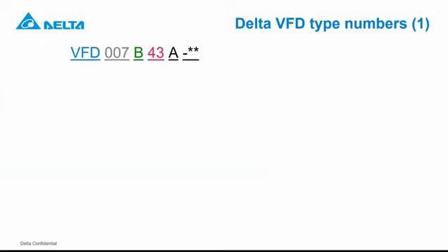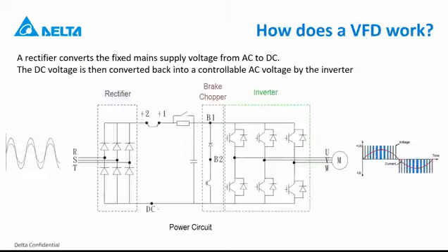How does the phase loss function work, since it can be powered on any phases? So I think firstly we need to clarify which phase loss we are referring to. You can have input phase loss, and in that case, if we are referring to the input phase loss, the drive will actually see that on the DC bus current.